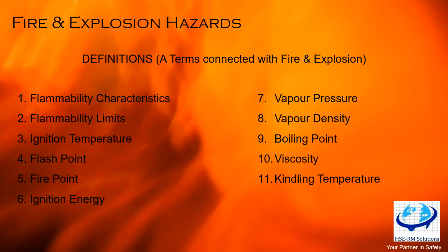At a higher temperature, it will definitely have an ignition point which is far lower than the actual liquid's flammable point. So you have to realize that any form, may it be liquid, solid or gas, with increasing temperature, the hazard also increases. This is the reason why, wherever stores are there, they say you need good ventilation so that the temperature remains at a lower level.